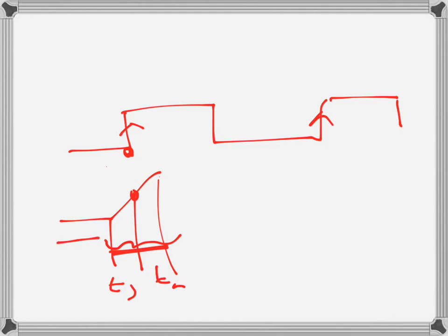It can change before that or after that, then it doesn't matter, because if it changes before that, whatever input is here will be taken, so if it changes here, let's say it will be taken as 0. And if it changes after the whole time, it doesn't matter, because the clock has already accepted the input. So while it's accepting the input, before it's accepting and after it has taken the input for a certain time, the input cannot change. The input has to be constant during that time. So those times are setup time and hold time.